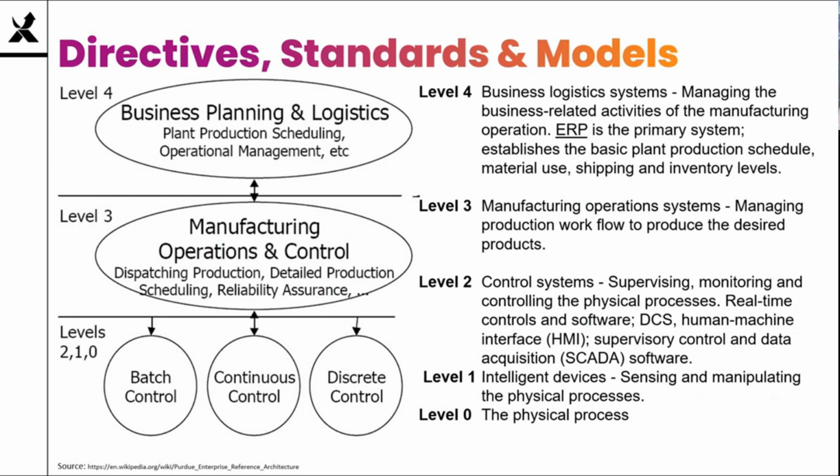As the arrows indicate, this is only the simplified outline, not all levels are allowed to talk to each other, whereas the IEC 62443 focuses on securing communication channels, minimizing the attack surface, and implementing strong access controls to protect against cyber threats. The Purdue model primarily emphasizes functional separation to prevent interference between the different levels of the hierarchy.